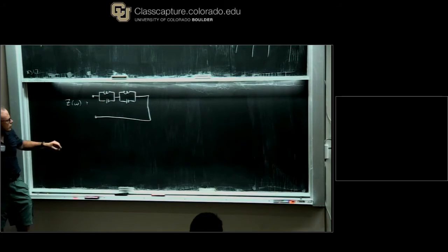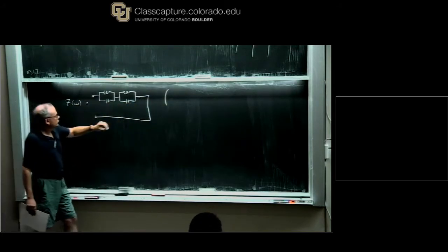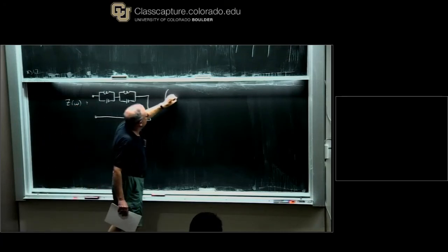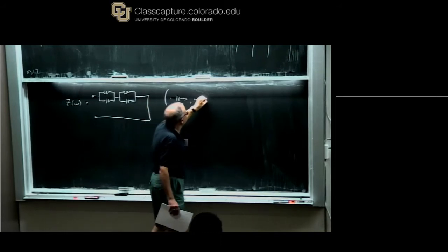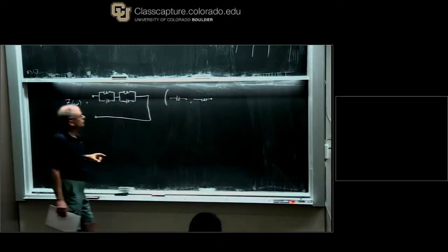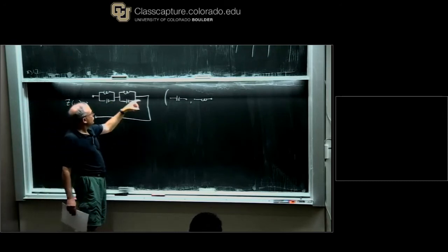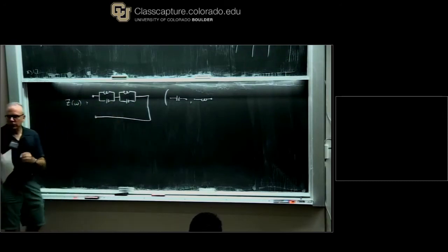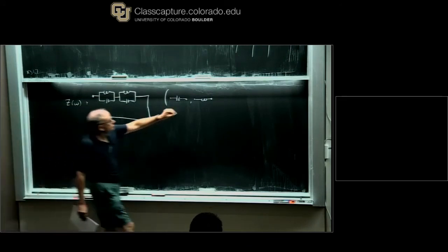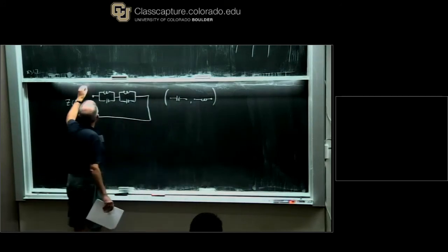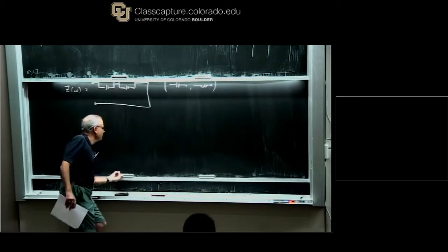You have to be aware that sometimes, and this is only a comment about the first couple of stages, you have a degenerate first stage, which is only a capacitor or only an inductor, or you maybe have possibly both. So the beginning may lead off with these, but it will then continue with an infinite number of simple LC parallel circuits. So this is Foster 1, and Foster 2 is a kind of dual representation.